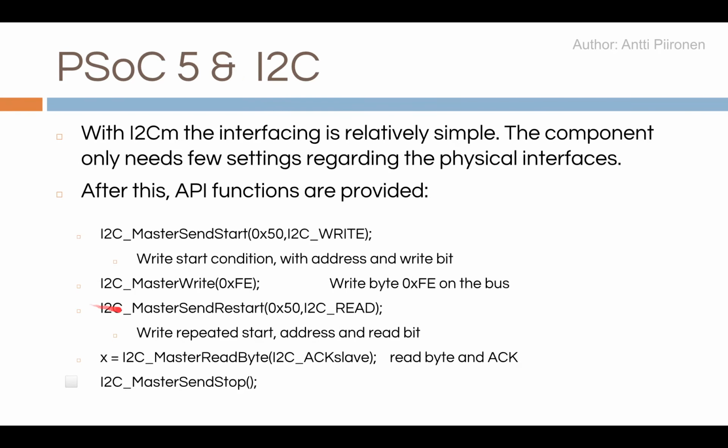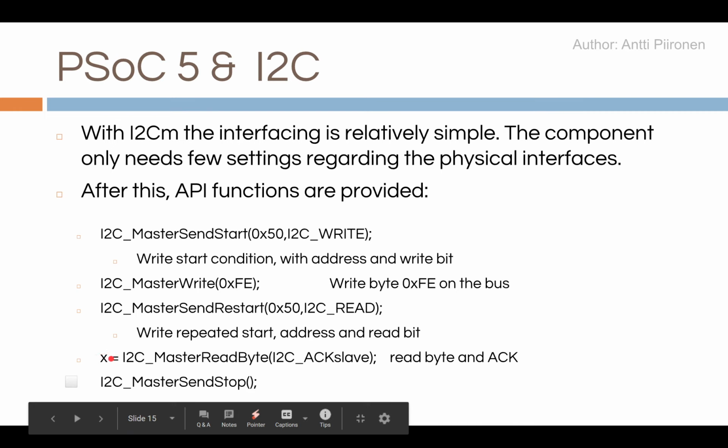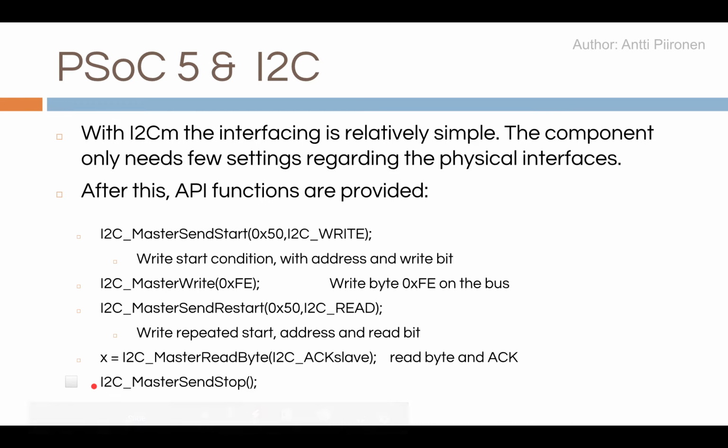Then you send restart and then get the data using the master read byte, with the acknowledgement, and then the I2C master sends stop. Okay, so that will be writing a command to read data from a device.